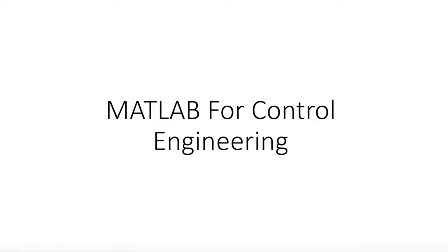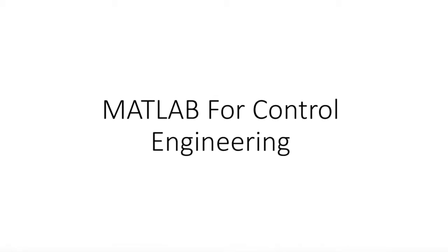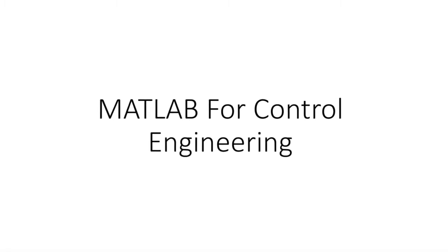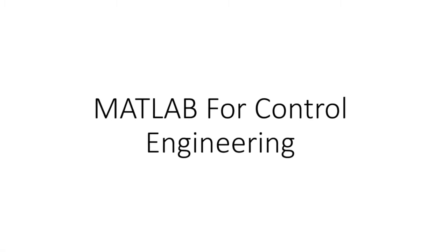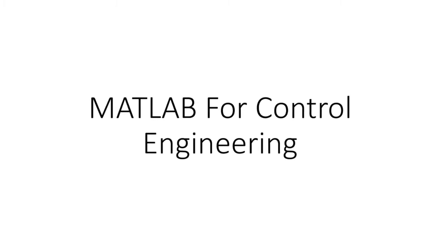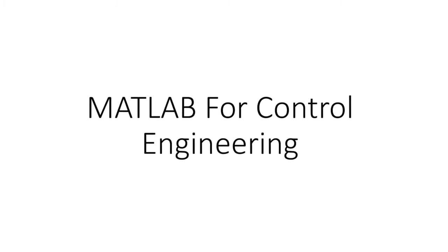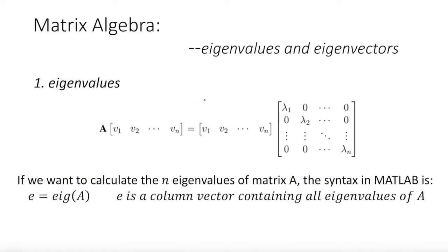Hello everyone, in this video we are going to provide some MATLAB examples about control engineering, and specifically about state space control and transfer functions. First of all, we are going to start with the eigenvalues and eigenvectors of an n by n matrix.